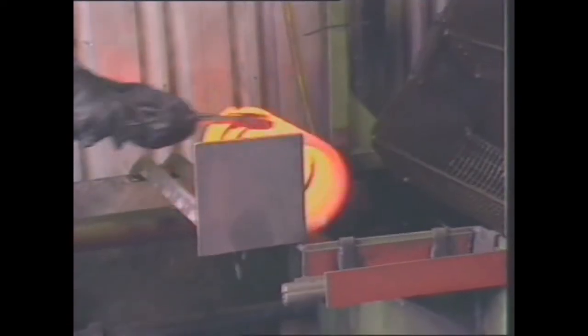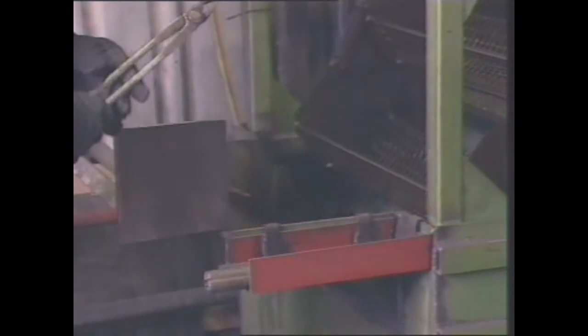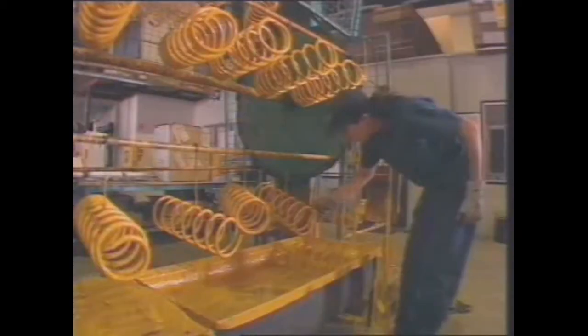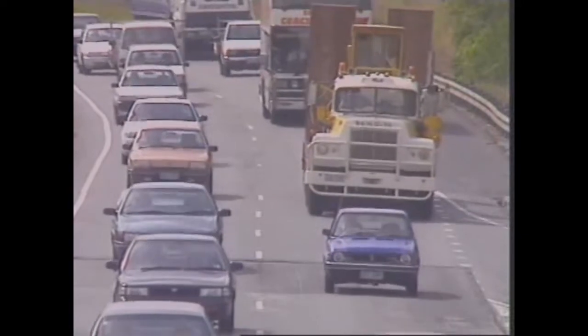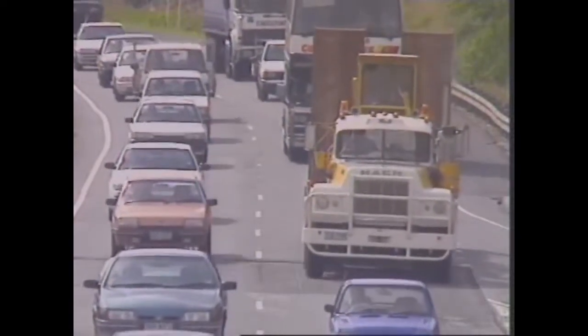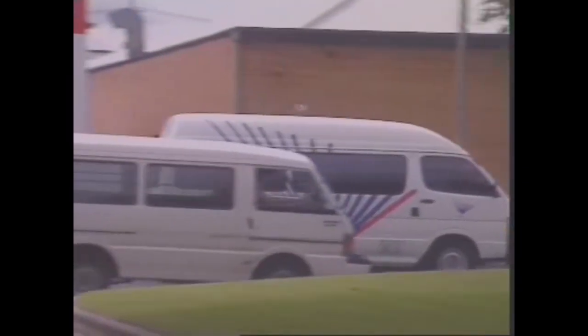The load-carrying ability of the spring depends on the diameter of the wire, the overall diameter of the spring, its shape, and the spacing of the coils. And this also decides which vehicle it is suitable for. A light commercial vehicle has springs that are robust and fairly stiff. On a small passenger car, they are lighter and more flexible.